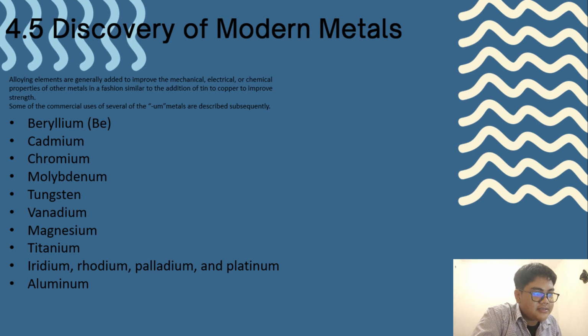The refractory metals are not compounds but have relatively high melting points. Because of its high melting temperature, molybdenum is used in the manufacture of high temperature heating elements and furnace trays. Work to develop molybdenum alloys for gas turbine application is one of many studies designed to obtain metals and alloys for every high temperature application.